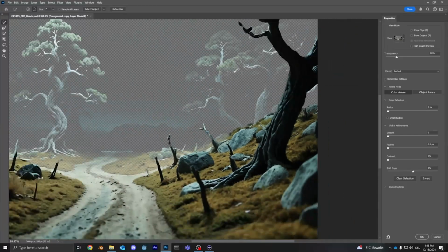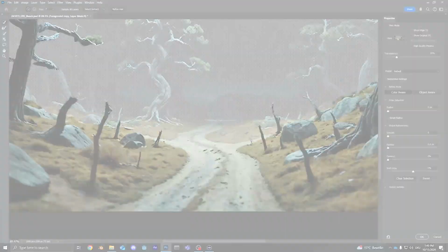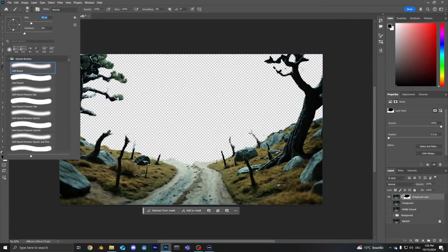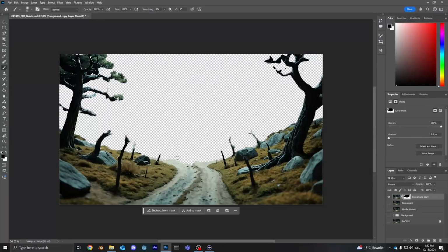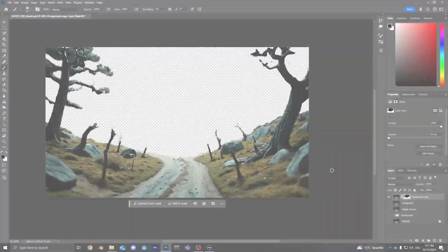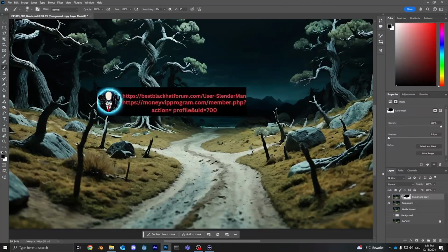And again, don't get too much into the details because this is going to be in Blender anyway. There's going to be moving camera and motion blur and all sorts of goodies that will distract your audience. And as a final suggestion, you can of course paint directly into this mask with your paintbrush. If you have a very soft paintbrush, you can make sure it's black and slowly go over some areas that you might want a little bit softer without the intelligent features that might also make mistakes sometimes. Same with white. So up here, for example, you're missing part of the branch. That's fine. You can just adjust that manually by painting into it. For the path, we're going to have to see what it looks like in Blender later. But for now, I'm going to try to make a soft transition.